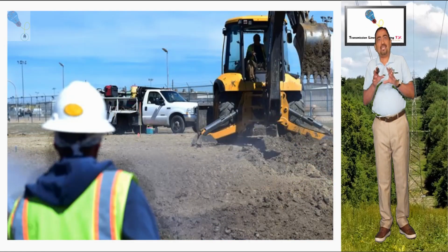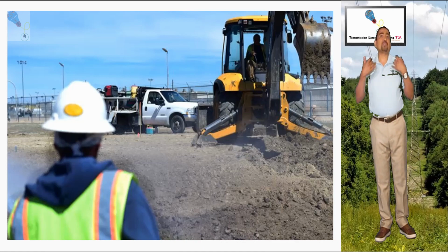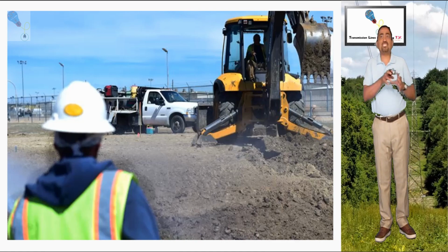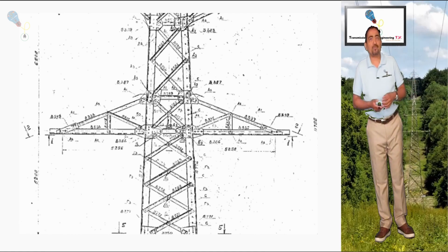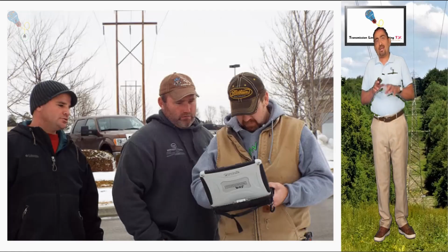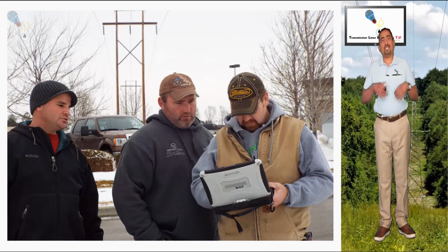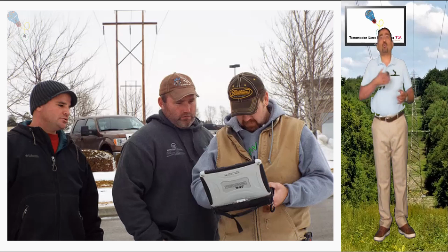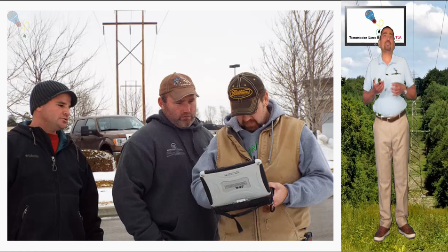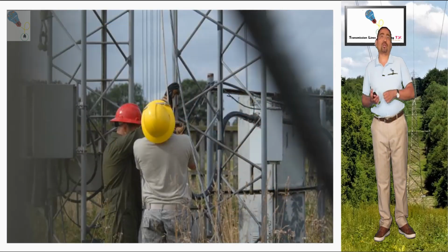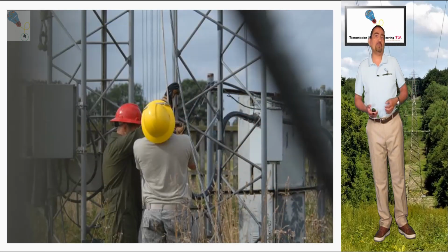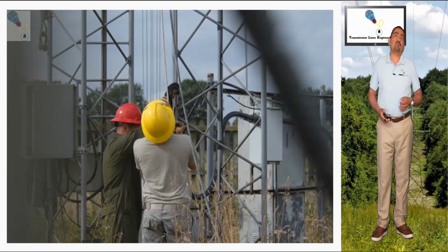For each activity, the quality discipline will be vigilant to ensure that the subcontractor is working with the latest revisions of each document because of the modifications during the construction process. As step number 23, once the construction is completed, or in those sections that have been completed, the construction, quality, and engineering teams must perform the line commissioning to review that the works were developed as indicated in the documentation. Step number 24.